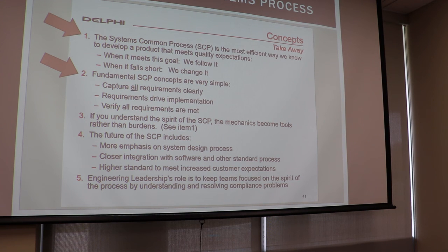Did you have something to say? I guess redundancies of the system. So can the whole system function if one of those sensors is obscured for some reason? What happens when one goes out? Exactly. So on my truck, I've talked about the automatic headlight thing, right? Well, if there's ice on the hood of my truck, it totally doesn't work.